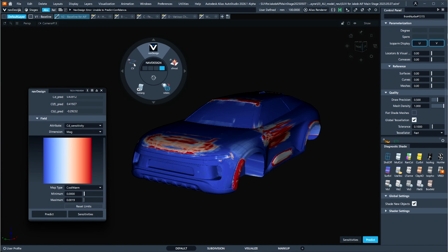What comes naturally if you evaluate such a model is also what we call a sensitivity. So you basically perform a backward pass through your network, sum up all the gradients, and then for each control point describing the surface, you also get a sensitivity. It's like a heat map. Which areas affect a certain